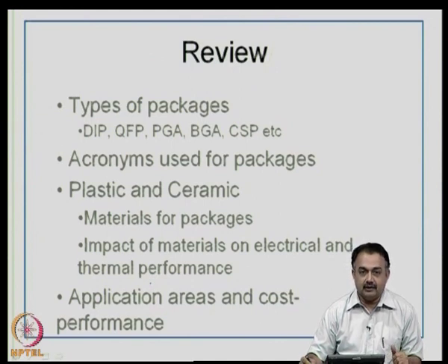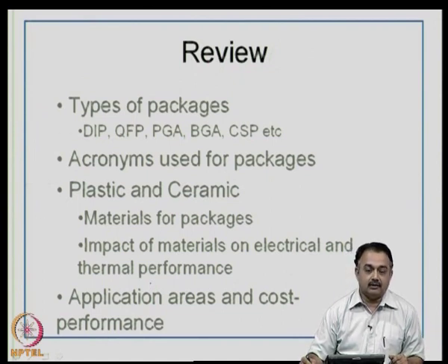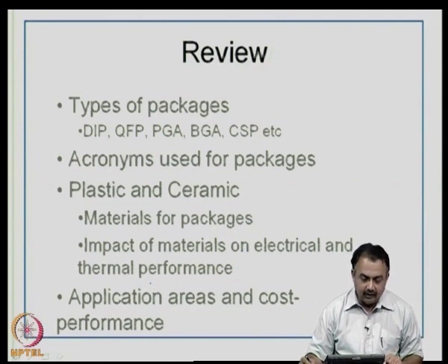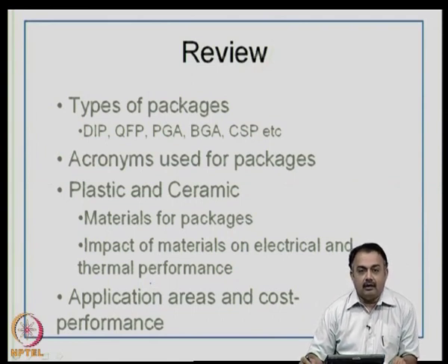live samples here, I have shown you each of these packages: DIP, dual inline package, QFP, quad flat pack, pin grid array, PGA, ball grid array, BGA, chip size package or chip scale package, etc. We have seen all of these packages, and we have spent some time on looking at